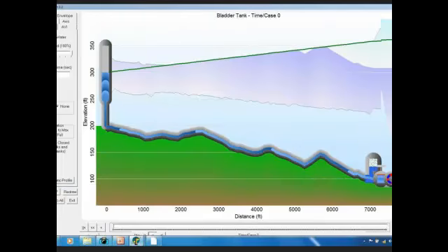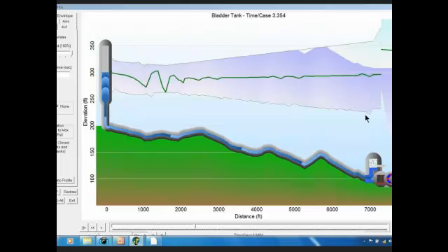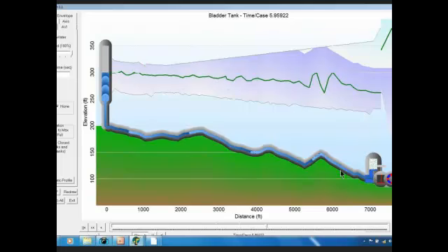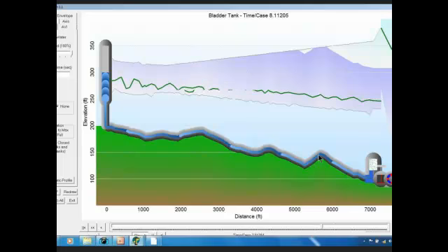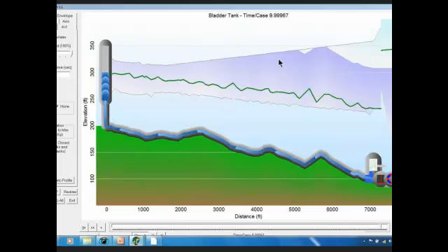Well, finally, here's a surge tank. Now, when the valve closes, you'll see the air push the water into the system, and it keeps the pressure from going down, and the air is going into the system, and you get the pressure confined to, this is the low pressure line, no negative pressures, everything works just great. So these animations would be very useful for looking at the effects of adding certain types of surge protection. And these are particularly good for a single pipeline.